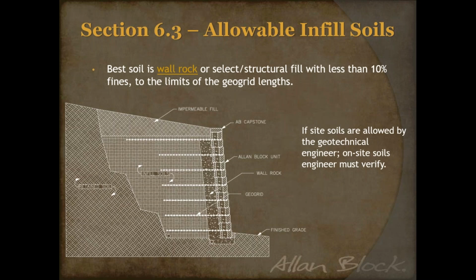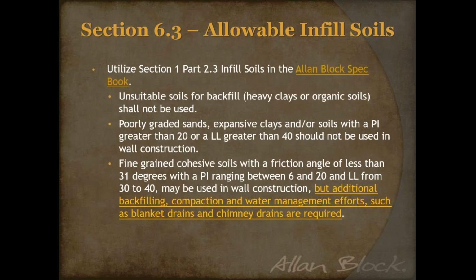Continuing with the infill soils, coming right out of our spec book, we know that unsuitable soils like those heavy clays should not be used there as well. Poorly graded sands, I mentioned that earlier. If I've got that beach sand or that sugar sand, those have a tendency to move on you, even with very minimal water being introduced. If you have that as backfill material, special considerations need to be handled. You might need to encapsulate that more with a fabric and not just use the conventional things. Obviously, expansive clays with a higher plasticity index can't be used when you have that fine-grained cohesive material.